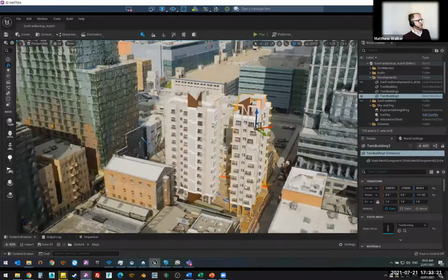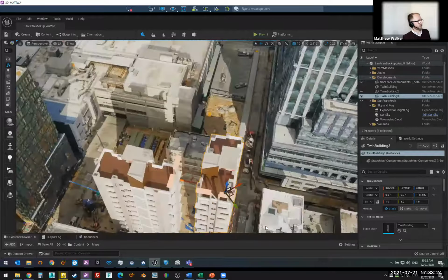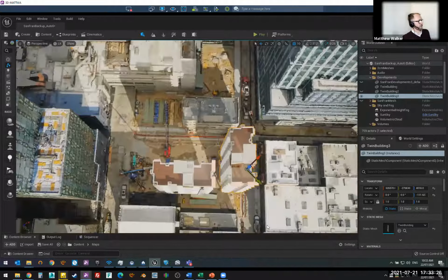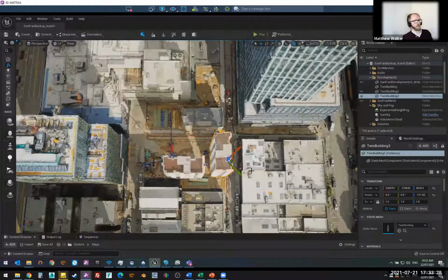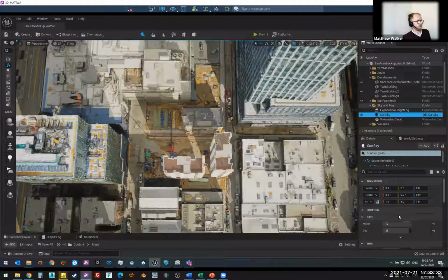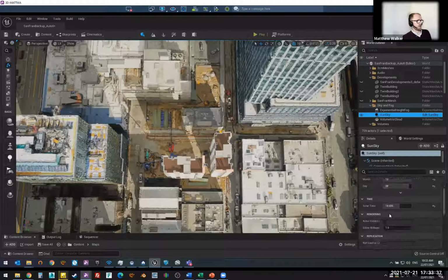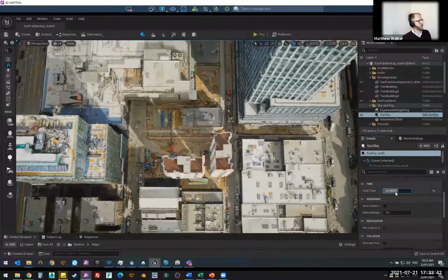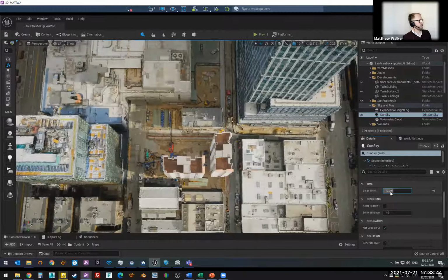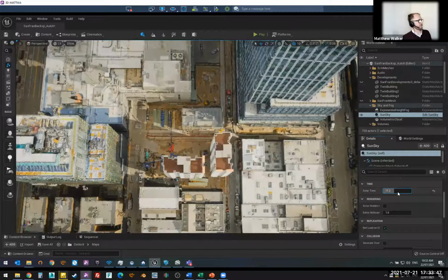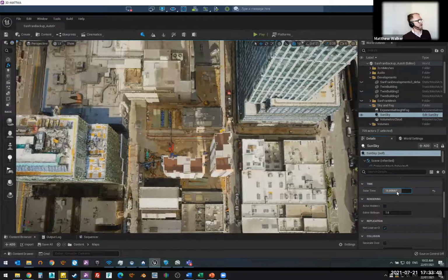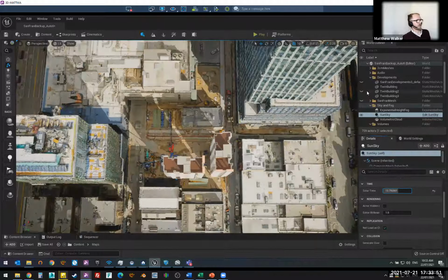So shadowing is one thing in Australia anyway that has a really big impact on certain dense areas. There's lots of constraints that we have here about overshadowing. Because we have a very accurate model, we know exactly where it's positioned inside the world. We've got it set up with the accurate time of day and the actual location. So we're able to look at the shadows that are cast at different times of the day and understand what impact these two buildings have on the actual environment surrounding it.